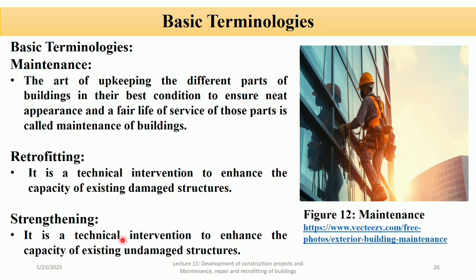Strengthening. So it is a technical intervention to enhance the capacity of existing undamaged structure. So we do strengthening to meet higher standards or new usage requirements and prevent future failure. For example, increasing slab thickness and adding carbon fiber reinforcement to beams.